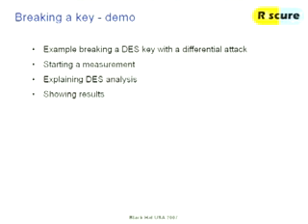The thing we are now switching to is a smart card. Why? Because it's a very bad smart card, which makes it very easy, well, easy is a big word maybe, which makes it likely that we can do it in a live presentation. Normally you do have to take a couple of thousand measurements maybe, which takes a couple of minutes to run, and then you need to do your analysis, so it all takes a little bit much time for such a presentation. However, with this card, we hope to do it in 500 measurements.